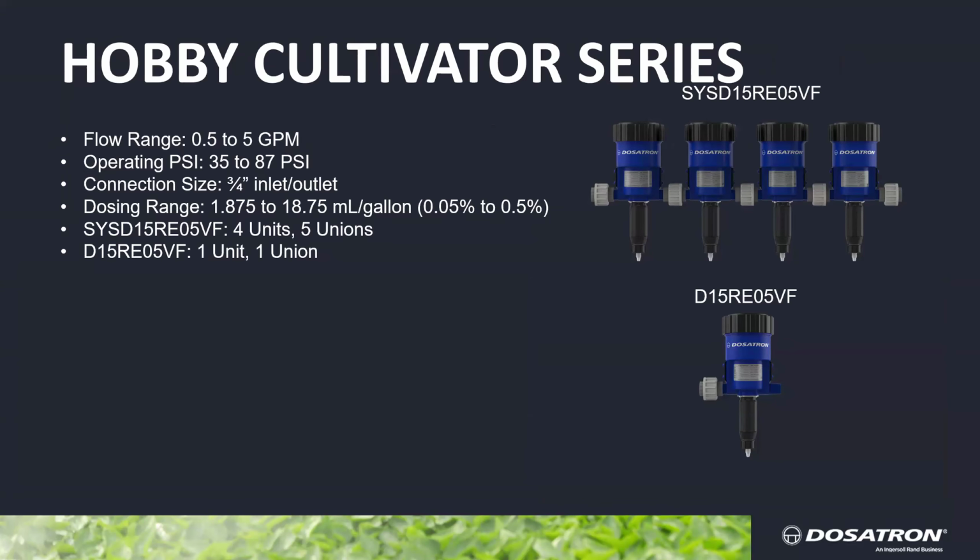So let's talk about some of the different Dosatrons that we have in the irrigation field here. The first is going to be our lowest flow range, and it is the hobby cultivator series. So our flow range on the hobby cultivator series is 0.5 to 5 gallons per minute. It has an operating PSI of 35 to 87, and it is a 3/4 inch inlet and outlet.